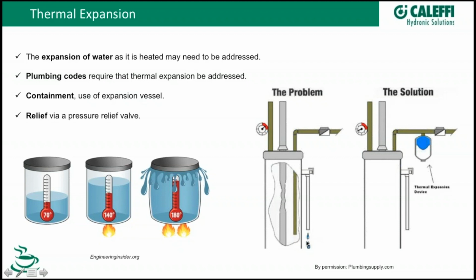So the valve will seep at first. If you see a valve that's dripping on your water heater, or a puddle near your water heater, you probably have this condition going on, where somebody's maybe added a backflow preventer or put a check valve somewhere out on the street that you don't know about. Your pressure's going up, and your valve's trying to protect this vessel. That's not really what we want this valve to do. This is really a safety valve. We don't want this to be a maintaining valve to take that pressure. And by the way, you're wasting water when you do this also. So a better way to do that is to put a thermal expansion tank in there. And what I found when I started searching through the codes is that more and more the codes are requiring this.